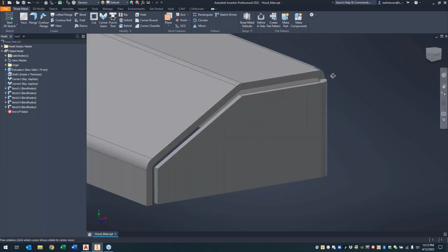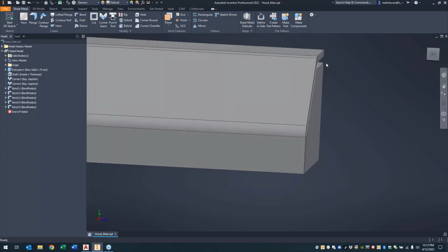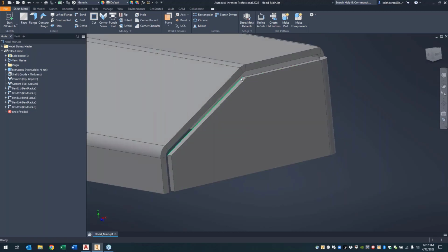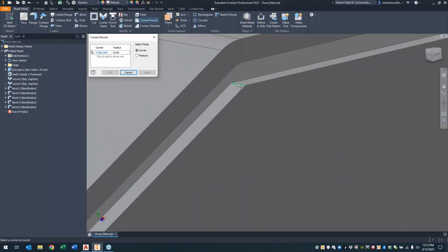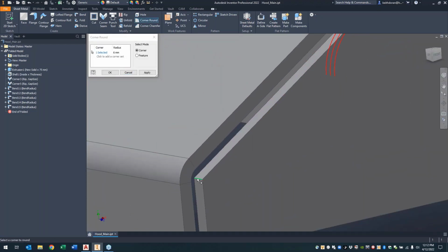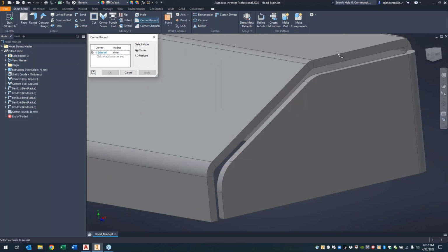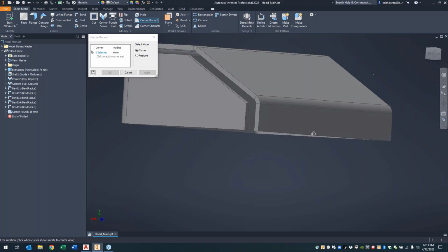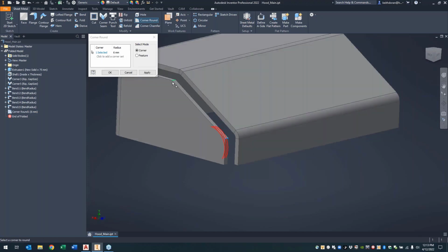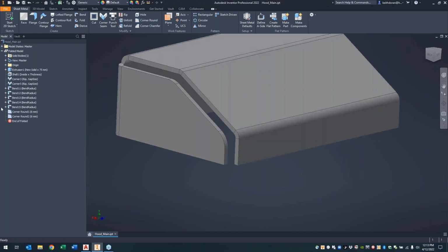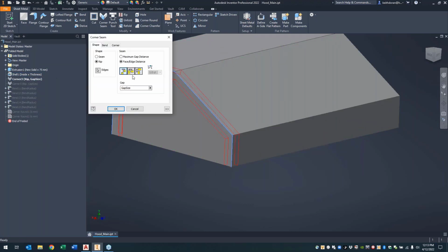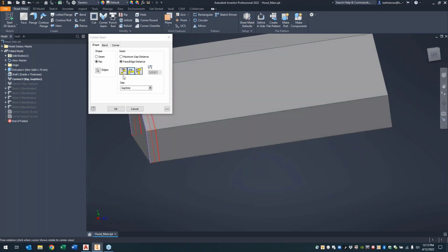So in this case, we can see it's pulled that edge flush over the top. From here, I could go in and close the gap size and put corner radiuses on this model in order to clean up that boundary, to help adjust the size of it on the part, so that I've got cleaner edges, no sharp corners at all. So I need to go in and just adjust this one. So edit the feature, push this so it's over the top.